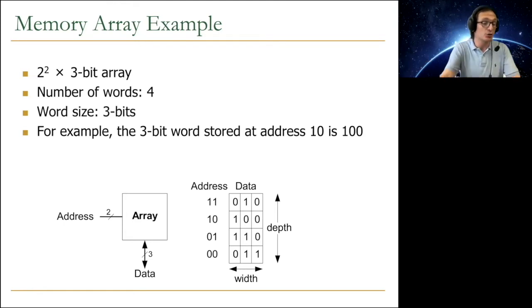As a result, because you don't read thousands of bits, you read literally 64 bits or so, because otherwise you'll have huge interconnects, and especially if you're reading off chip. Then you need to be very careful, because whenever you're reading off chip, you need to have pins to go out of the chip, and those pins are extremely costly, and you may not even have thousands of them, because they occupy a lot of area. Your chip may not be able to accommodate thousands of pins.